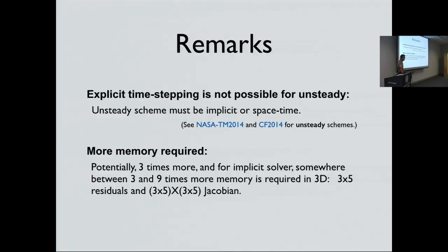But you ran the cylinder, which had a curved boundary. I used a linear element, just a linear segment. It's talking about P2 element, P3 element. Yeah, the triangle with curved edges. Oh, you don't know if you got curved interactions. I think I will lose third order like this. You don't know the exact solution to the cylinder. No. So you don't know. Have you got a method of manufactured solutions? Yeah, so that's why I'm doing that.